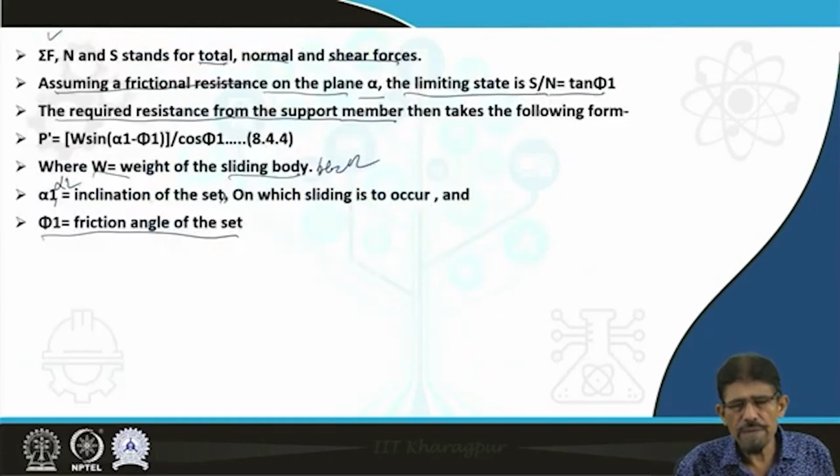In this way, we have discussed the structural defect approach or block theory, because here deformation commenced in form of movement of block under influence of gravity, and the movement of block is going to create the empty space for movement of the other block. In this way, the whole rock mass is going to show some deformation, and finally the created opening got cleared.